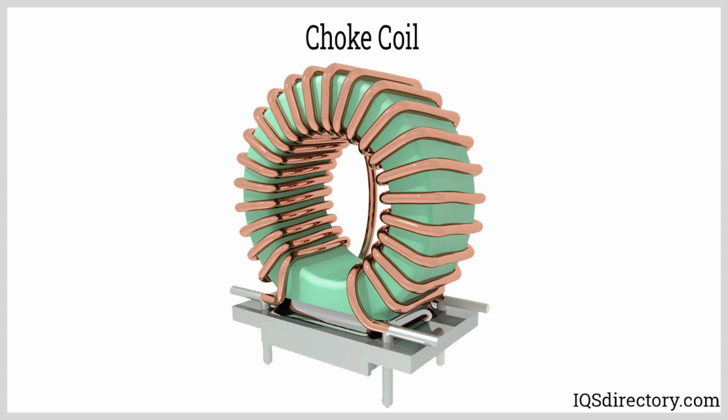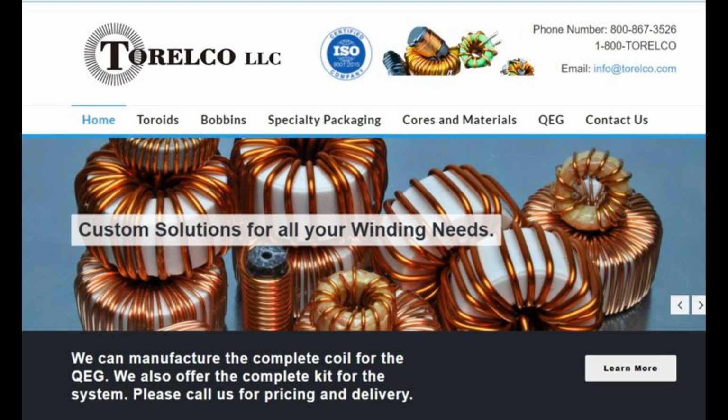In modern fuel-injected engines, chokes are largely obsolete. Fuel injection systems use electronic sensors and engine control units, ECUs, to automatically adjust the air-fuel mixture for optimal performance during cold starts and regular operation. These systems provide a more precise and efficient way to manage the engine's fuel mixture without the need for a choke. Advantages of the engine choke.